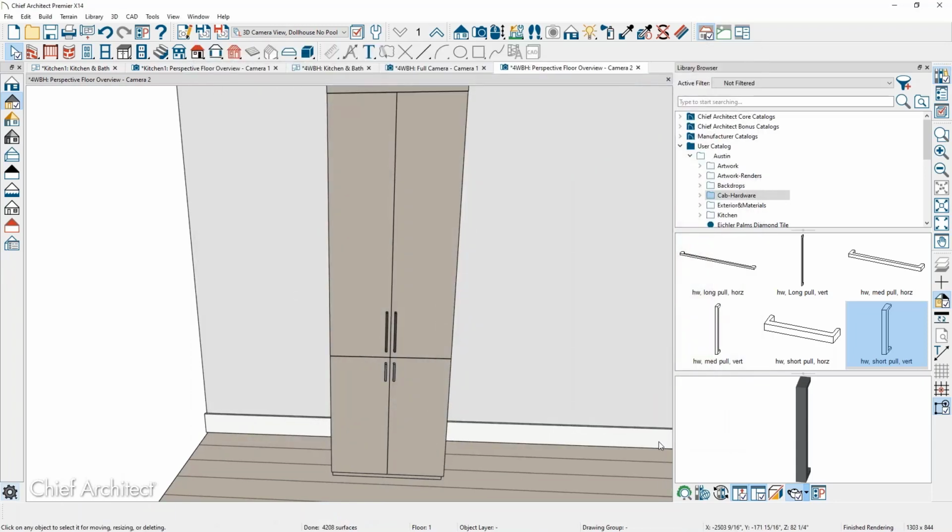And probably that would be flipped around where the smaller one's on top. If that works for you, you could set that as your default, and then for the rest of this design, it would use the properties for that tall cabinet. Or if you have unique tall cabinets throughout the design, you just have to open it up, make the adjustment, and just go through the appliance door specify.